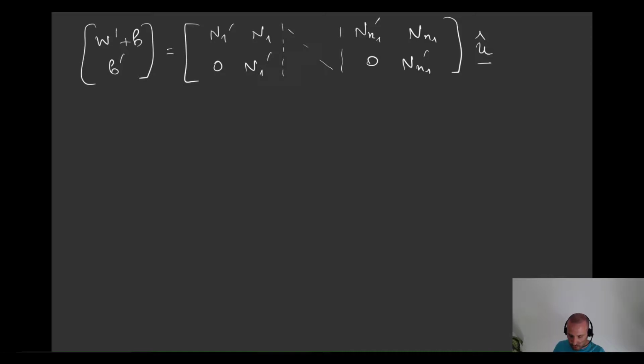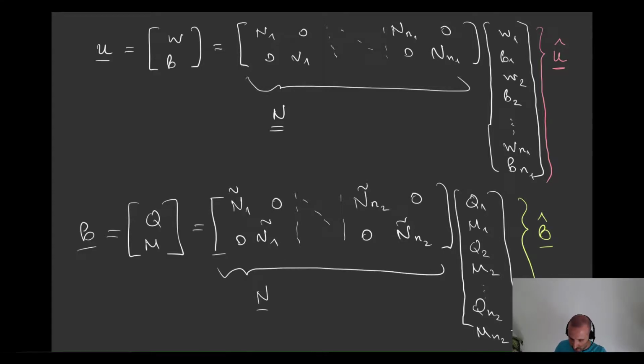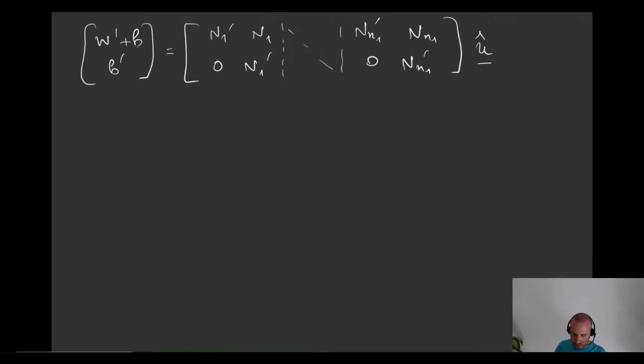And now I would like to give some names to these matrices. So this matrix here, I would like to call it the shape function matrix N. Okay, this down here, I'm going to call the shape function matrix N tilde, which is associated with the secondary unknowns. So the N is associated with the discretization of the primal unknowns, and the N tilde matrix here is the shape function matrix associated with the discretization of the secondary unknowns. All right, now having all these constituents, we can also give a name to this one here, but I think that should be clear because this is the B operator matrix we had in the beginning of the lecture. So this is nothing else but